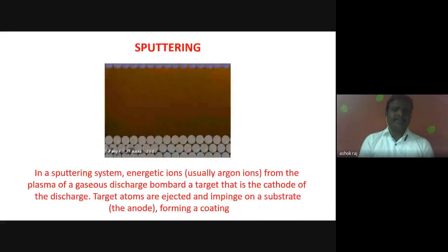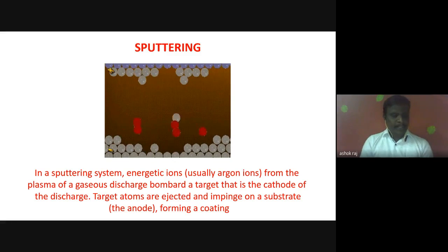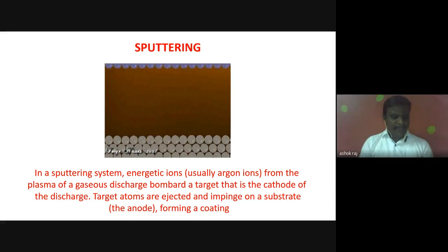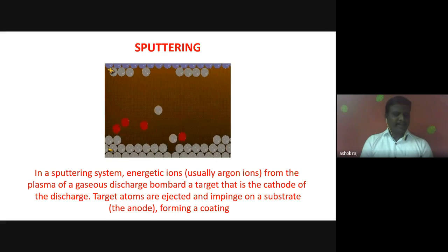The next famous process is the sputtering process. Generally, the sputtering process is considered to be one of the most versatile thin film deposition techniques. It is a process whereby atoms are ejected from a solid source material due to bombardment by energetic ions, usually by means of plasma, which generates charged particles that are accelerated towards the surface, which is shown here in animated form. It produces coatings of device quality, higher purity, much controlled thickness with greater adhesion and great morphology of the thin films.